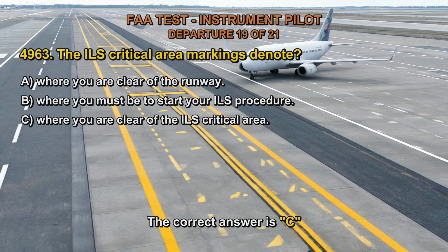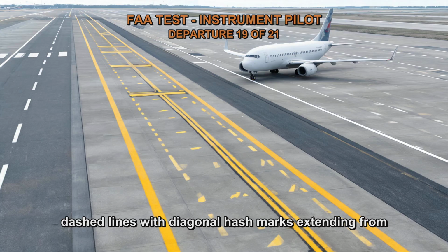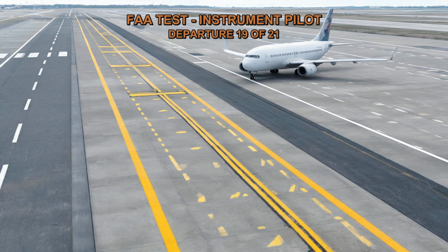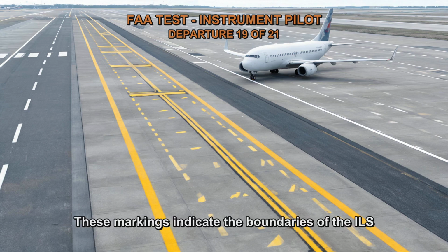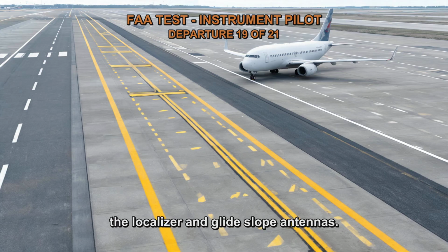The correct answer is C. The ILS critical area markings are typically yellow dashed lines with diagonal hash marks extending from the runway holding position to a designated distance. These markings indicate the boundaries of the ILS critical area, which is a protected zone around the localizer and glide slope antennas.